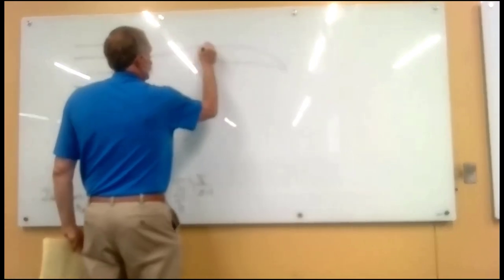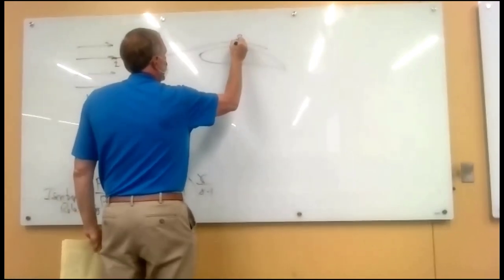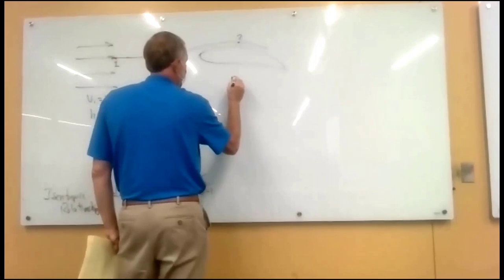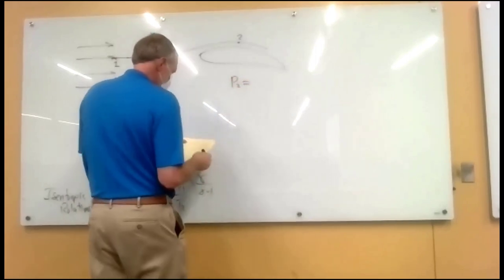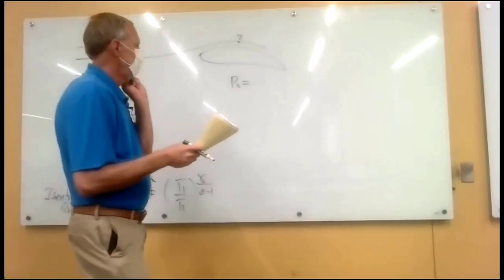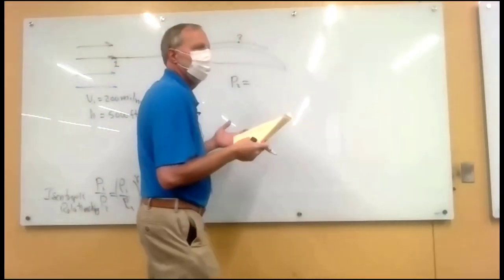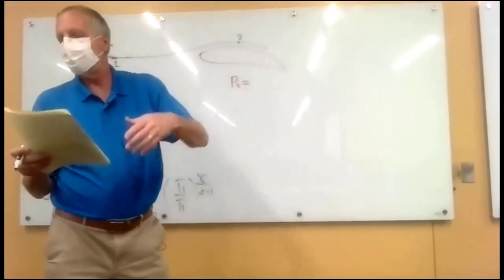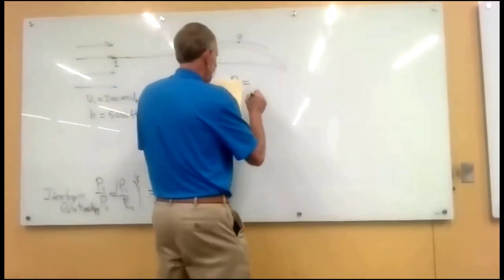And one of those streamlines goes around, and at a position here, we measure pressure, because that's easy to do. It's easy to put a pressure probe in the flow. If you try to measure the velocity, how do you do that? You put a little propeller, and that's going to slow the flow down or affect it.